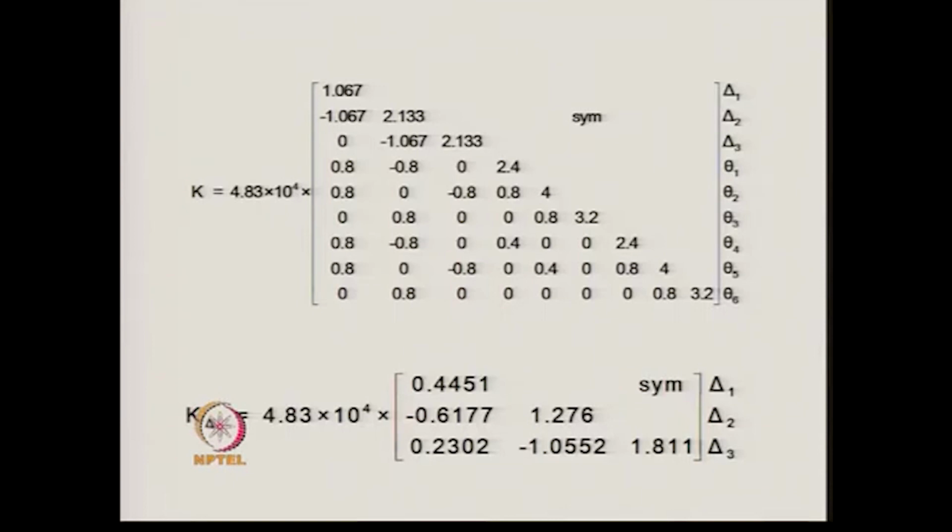We have made sure that at the two ends of the bottom beam, or the first story beam, the moment coefficients will be equal to 0, because we consider an ordinary hinge there. After we have written down the total stiffness matrix, only then we condense out the rotational part of it and land up with the 3 by 3 stiffness matrix, that is the condensed stiffness matrix.